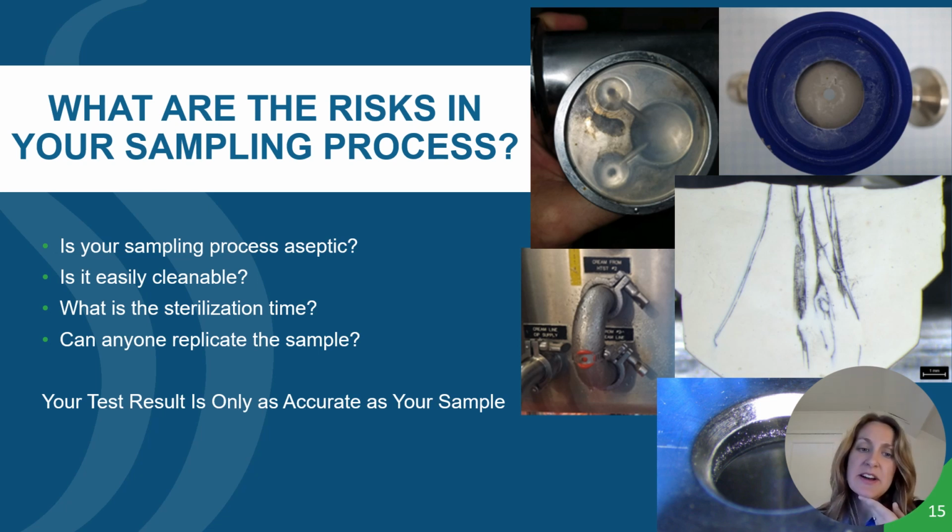So what are some considerations that you have when you think about sampling? The first one you want to ask is, does the sample need to be truly aseptic? What decisions are going to be made with this sample? Next, if you decide that you need to have a clean sample that prevents contamination into your process or into the sample valve or sample vial itself, is it cleanable? How easy is it to clean? Do you have to take it out of place? Do you have to require steam to clean it?